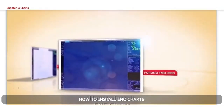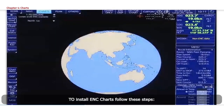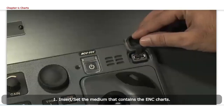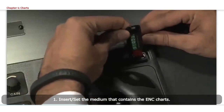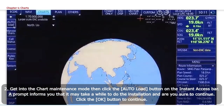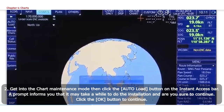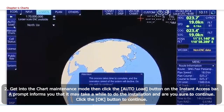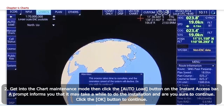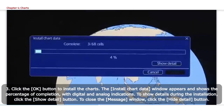How to install ENC charts. To install ENC charts, follow these steps. 1. Insert or set the medium that contains the ENC charts. 2. Get into the chart maintenance mode, then click the Auto Load button on the Instant Access bar. A prompt informs you that it may take a while to do the installation, and asks if you are sure to continue. Click the OK button to continue. 3. Click the OK button to install the charts.